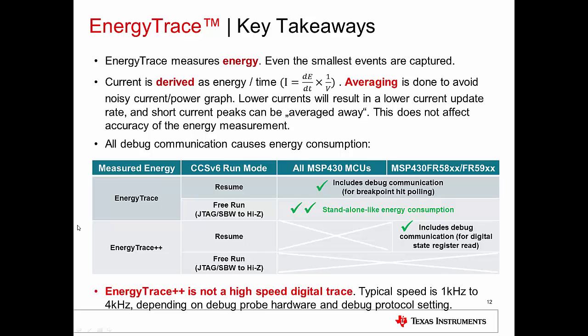Also keep in mind that EnergyTrace requires debug communication to transfer CPU or peripheral state information back, and this can add to the energy consumption of your system. So if you look at this graph here, in the EnergyTrace mode, which is where you just measure current only, if you just click resume in CCS, which is the play button, this includes all the debug communication.